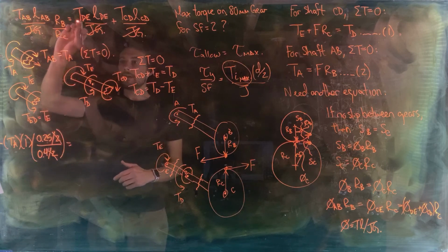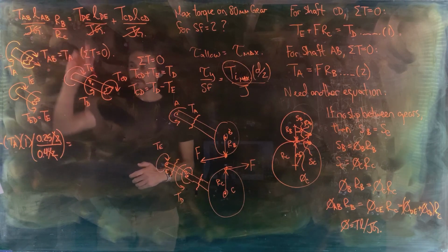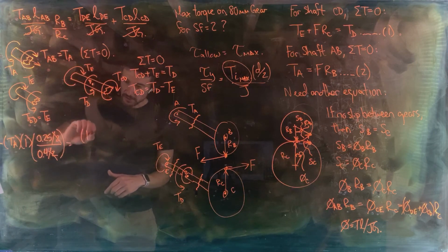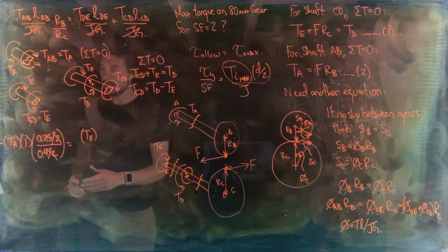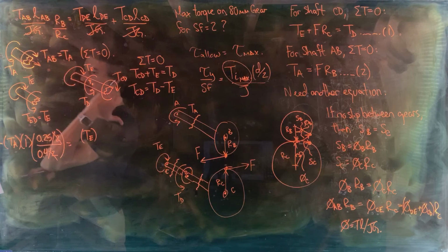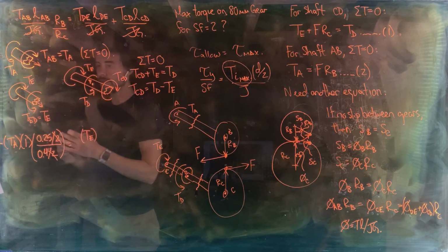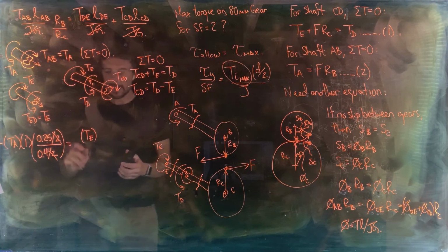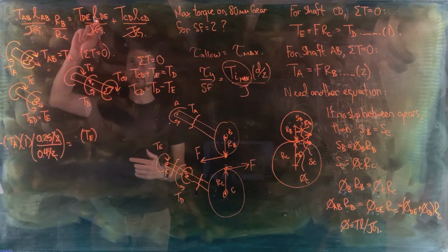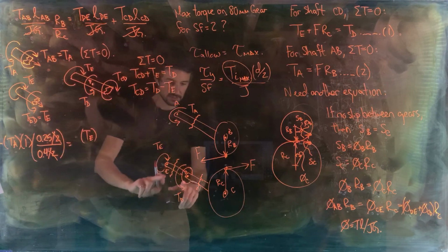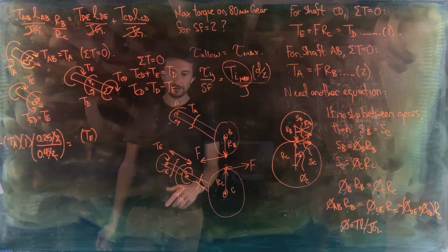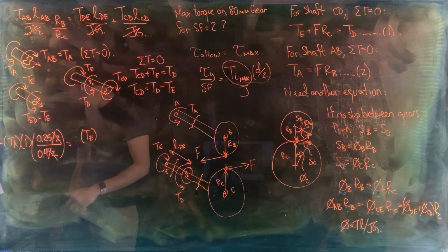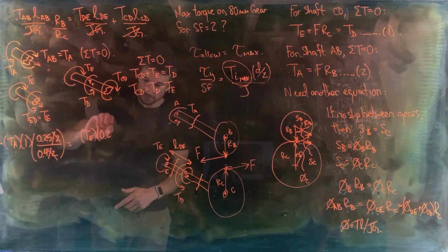So then on the other side of the equation, TDE now. TDE is right here, and it's equal to TE in magnitude. Again, direction makes a difference, so use your right-hand rule, thumb pointing out from the section cut in that direction. Your fingers curl in the direction of TE, so that stays as a positive value, and then we multiply by the length of segment DE, which is just that length there. So here's LDE. And that from the earlier diagram was 200 millimeters, so 0.2.